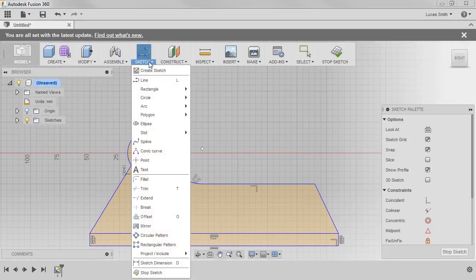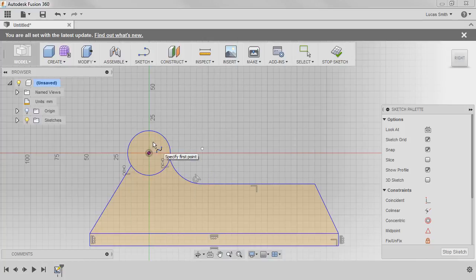Next, I'll use the spline command to draw the handle. As I draw the spline, I need to keep in mind the whole shape I want to end up with, since the entire spline will adjust as I add more spline points. If needed, these points can be moved around and the tangent lines adjusted to create approximately the same shape.